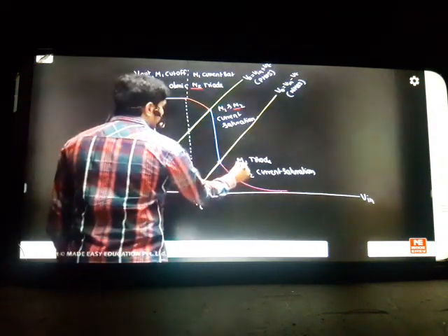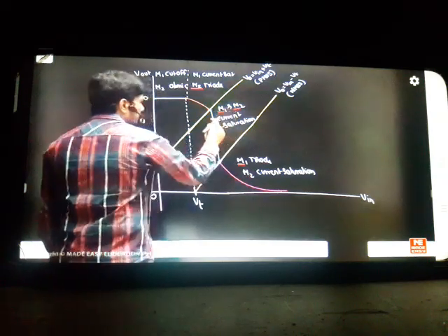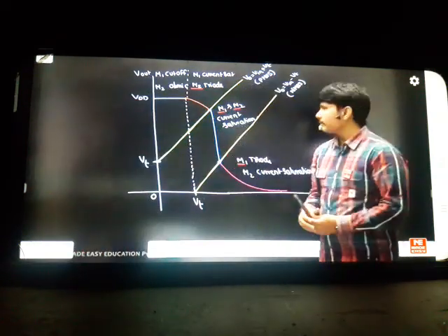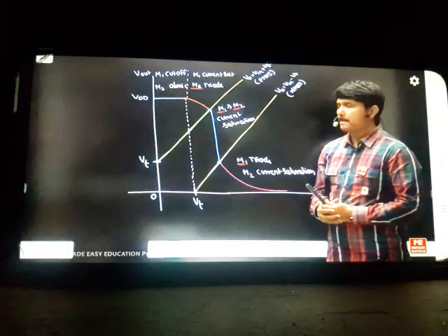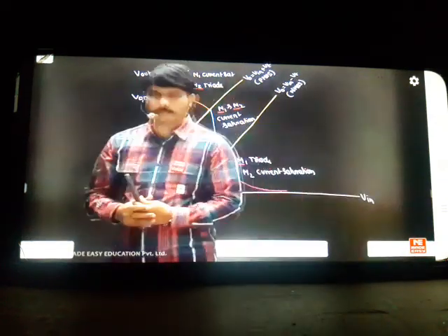Okay, M2 goes from triode to current saturation. But whenever you come from this line to this line, can you see that here what is changing is M1, changing from current saturation to triode. Like this, you have two transitions going on. When you touch this line, one transistor will change its transition. When you touch this line, it will change the other transition. This is your CMOS graph technique.